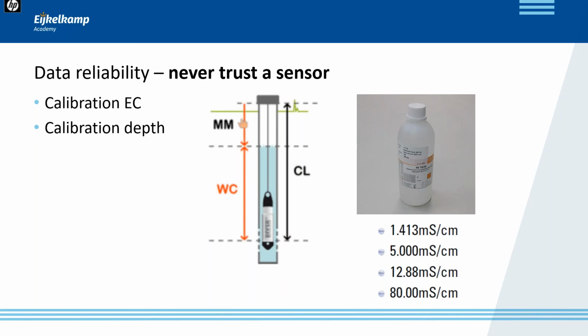If your depth measurements are performed by a pressure sensor, be sure this sensor gives you the correct data. The performance of a sensor must be checked by a manual measurement of the water level. A pressure sensor above the water should give you a pressure which is equal to air pressure. And secondly, it is good to realize that a pressure sensor is not the same as a measuring tape. It acts differently. All sensors do have offsets and can suffer from drift.